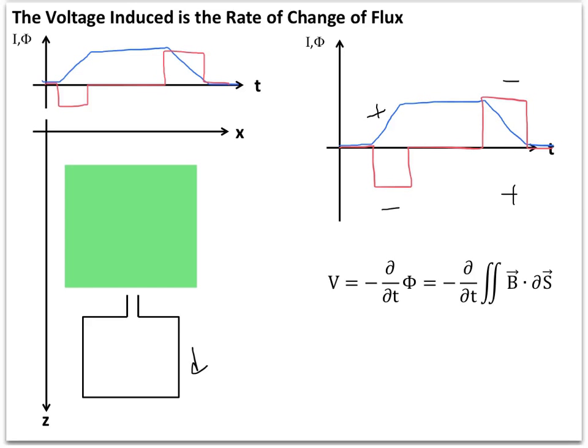And so we can write this in this form right here, because it turns out that it's not the current that's generated, and this was verified experimentally. The current is actually generated by a voltage around the loop. So Faraday's law essentially states that the voltage around a loop is equal to the time rate of change of the flux, and of course we can just write the flux as the time rate of change of the magnetic field.